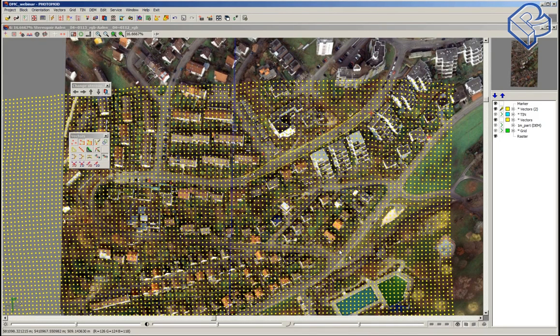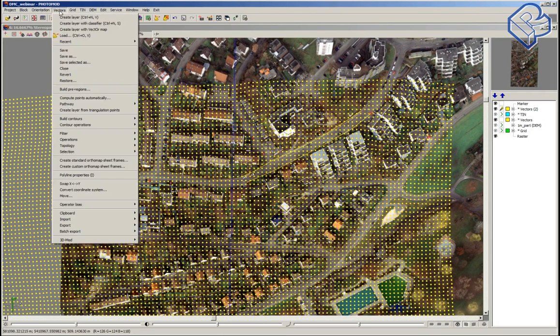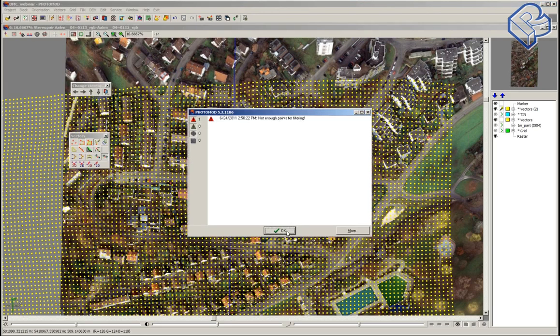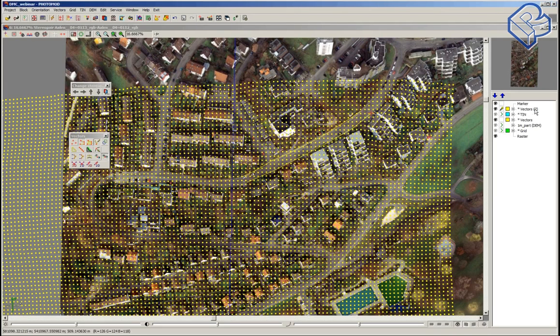And the next question is about parameters. What parameters should we use for filtering points? Let's look at the settings window for filtering again. Vectors, filter, buildings and vegetation filter. Oh, because it's a layer with lines, just activate the one with points.